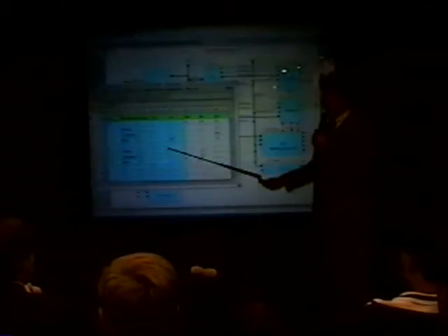The other editor we have available is called Truth Table Editor, which gives you a spreadsheet-type capability for capturing your design functionality. You can enumerate out the values of the inputs, which are shown here in the blue, and then set the outputs to the corresponding values. This is a very straightforward and simple way of capturing combinatorial logic.